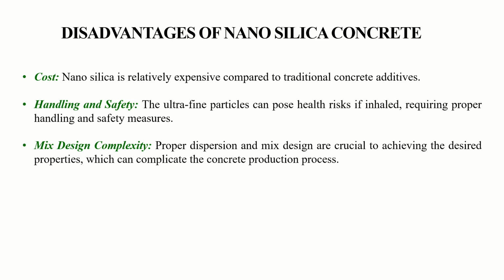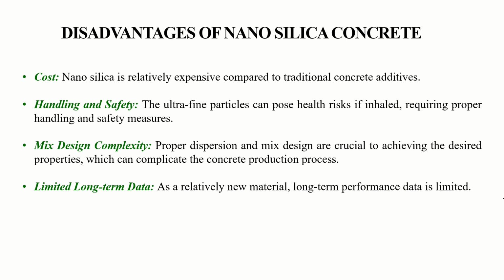And coming to the mix design complexity, because of the very small and fine size of the particles, dispersion and mix design have to be looked at very carefully, because we may get workability issues and consistency issues. So we have to be very careful when we are replacing cement with nanosilica.